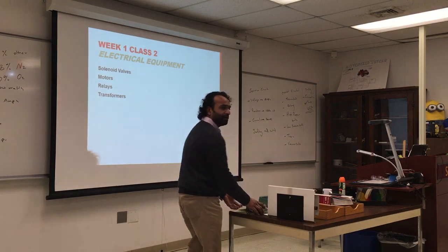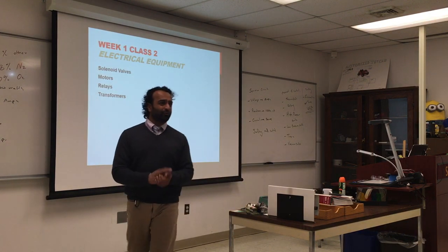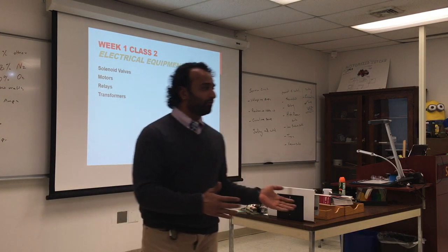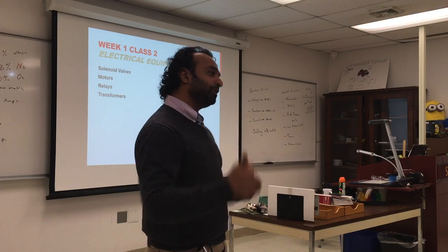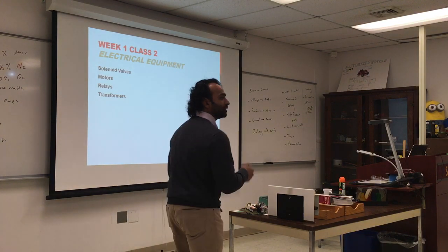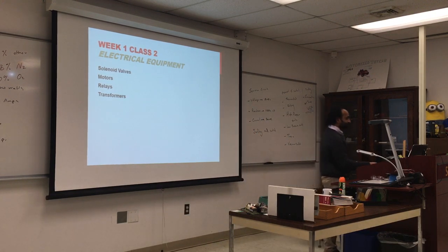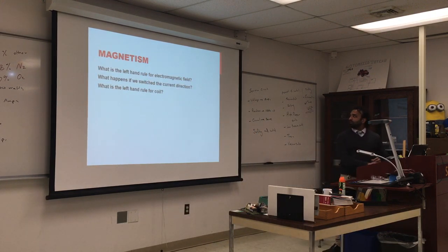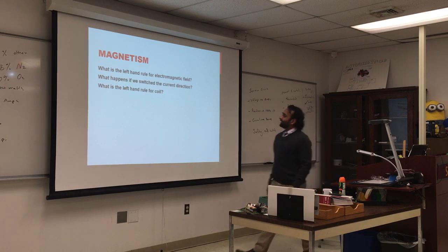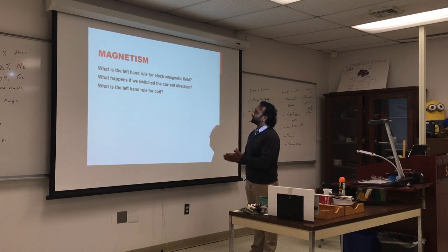So for our purpose, usually it's going to be 24 for control. So 120 to 24. Sometimes you might have 220 to 24. But again, that's what we need control transformers for. Okay. We talked about that plenty last semester.